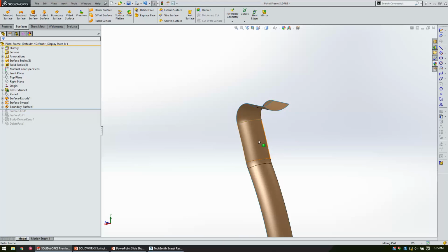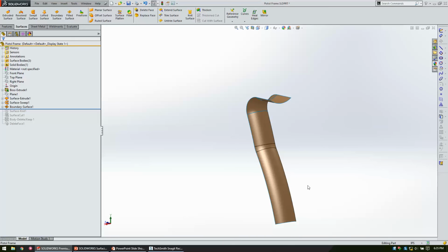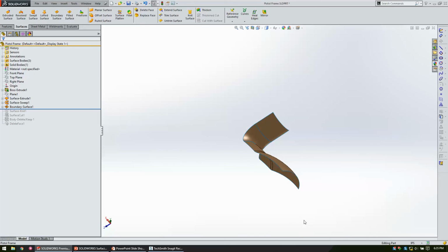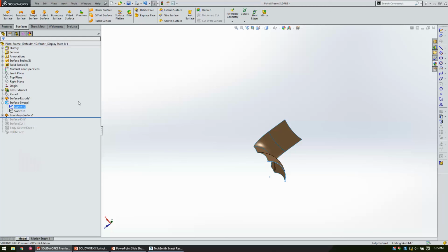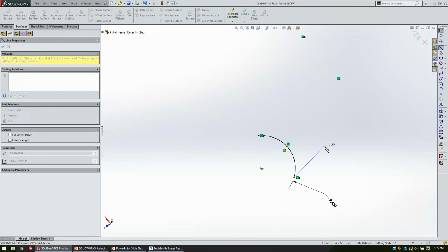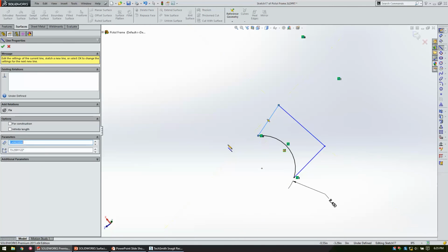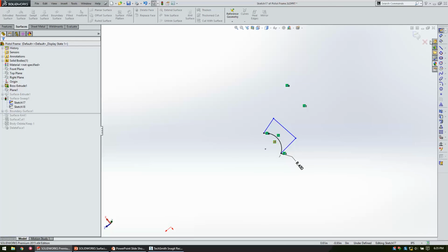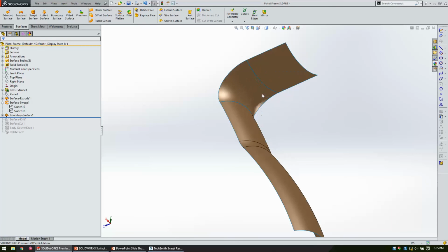So you can see this would be very difficult to do with solid sweeps or solid lofts. Because if I'm going to sweep this, I have to define my z-axis, as we're calling it. I would have to draw something that comes up to here to create an enclosed volume. But I'm going into such a small space in the corner here that that's kind of difficult to pull off, because that other distance then tends to self-intersect when I sweep that corner. And then the loft is kind of weird, because the loft is pulled and contorted based on the other 3 sides that I could care less about.